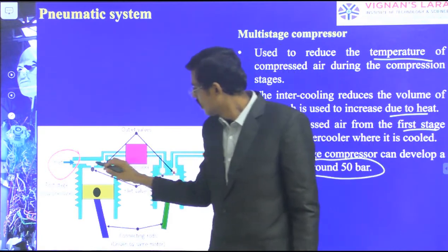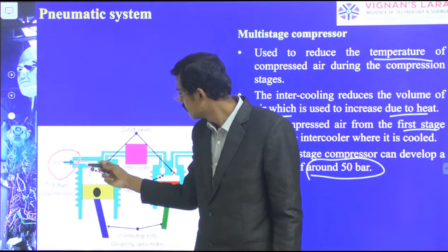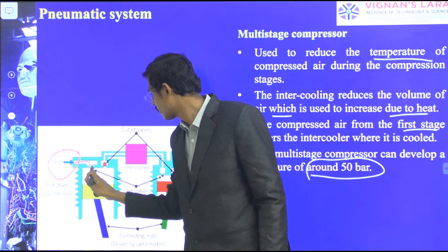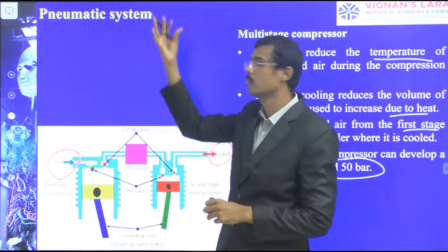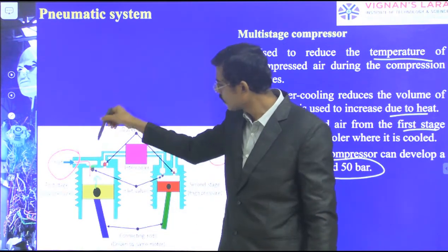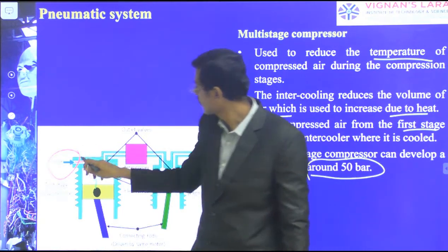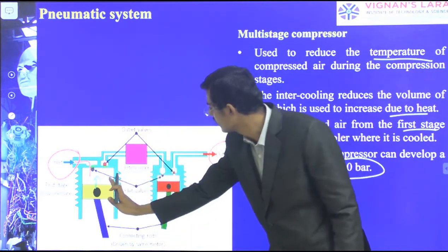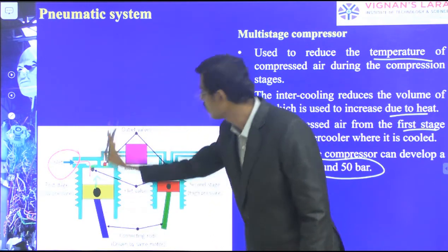You see, first inlet is coming here. This valve is kept below this zone. You see, it is straight. It is not permitting, and the valve can open in the downward direction only. It cannot be moved upward when the piston is going again in this direction. So only inlet is possible. But see here, this valve is operated at the above point. I am closing again the above point. So this air, when it is compressed, goes through the upward direction only.